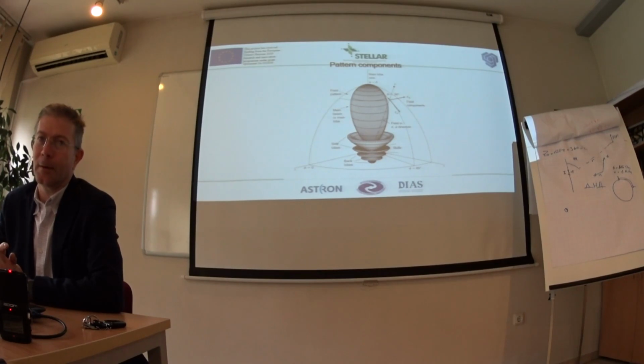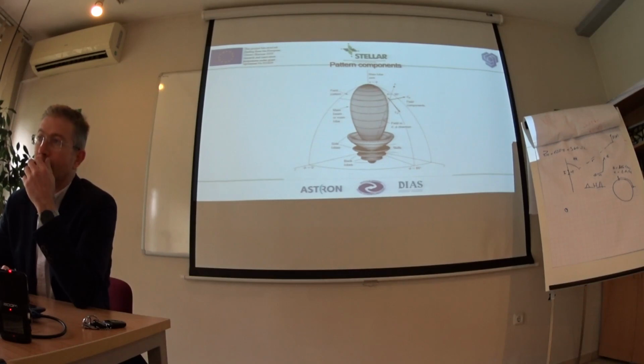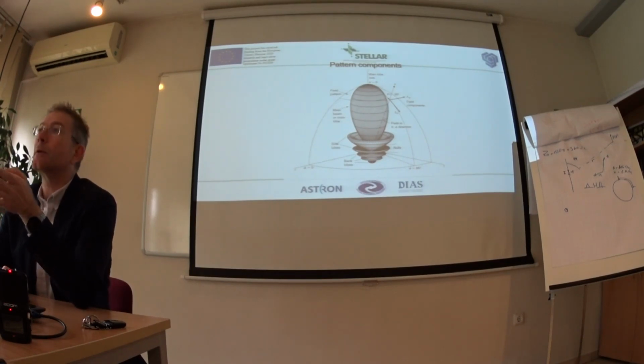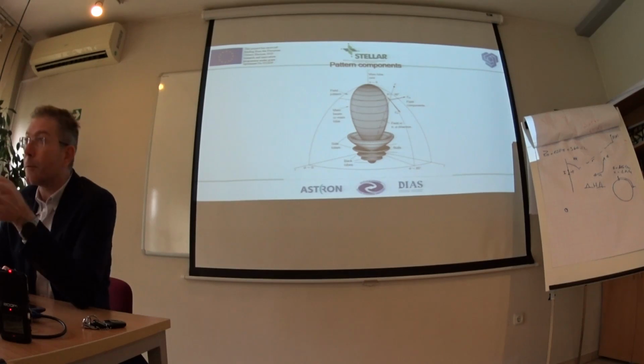This is the components of the antenna radiation pattern. In what radiation zone are these small emissions that we can classify? The small emissions near the antenna itself. Yes, they're called side lobes. The side lobes. Yeah, but in what reactive zone are they? Everything you see is in the far field. In the near field, there is no pattern like that. Okay.